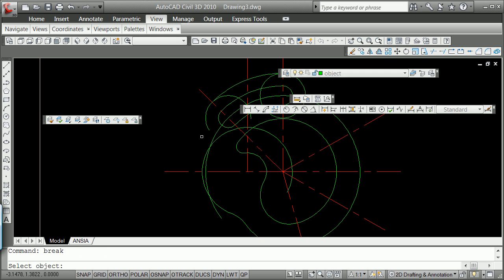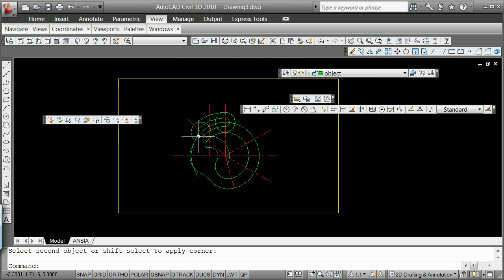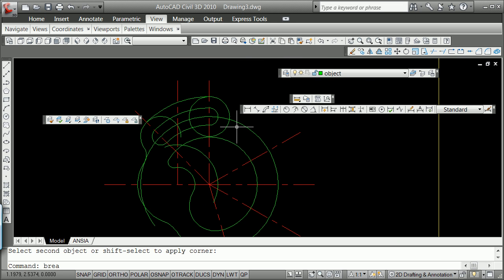So we're going to do a break here. Remember, in a positive direction, we're going to do a fillet radius of, like all of them, 0.63. All unmarked radii are 0.63, and we've got that filleting into that one. And you see it almost just kind of touches it as it is there. So that one comes around here. We're going to break this here.